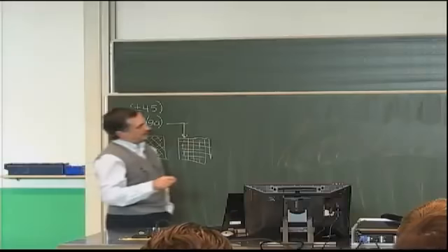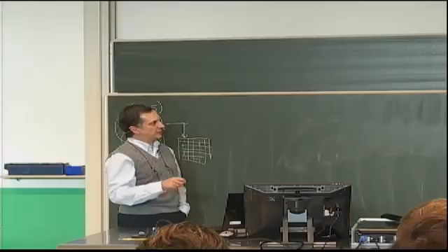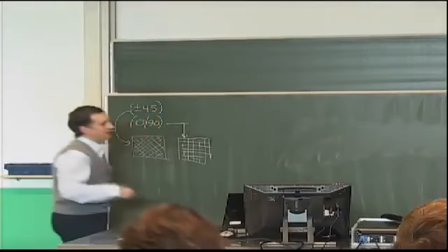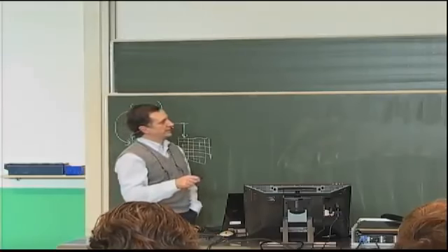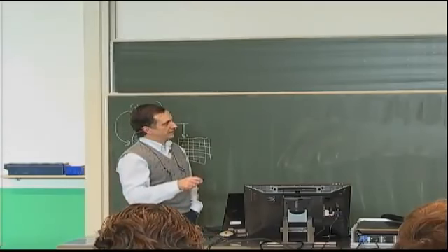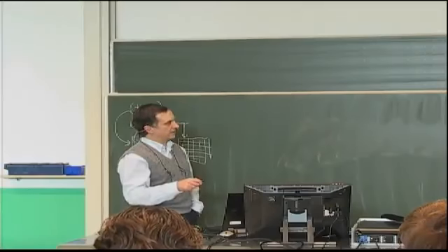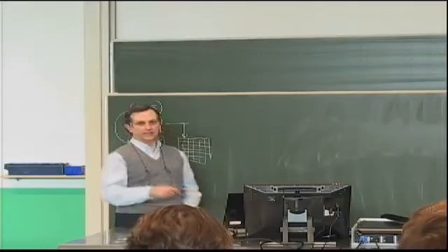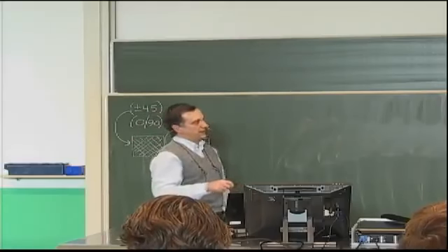Now, each of the moments can now be replaced through our ABD matrix relationship. And because we said the B matrix is 0, then it's just directly involving the D11, D12, D16 terms, and so on. And because I said D16 and D26 is 0, I can replace these moments with these products, D11 times kappa x plus D12 times kappa y, and so on. When we do this, we arrive at exactly the same left-hand side that I just showed you from before. And the right-hand side is still my out-of-plane load.